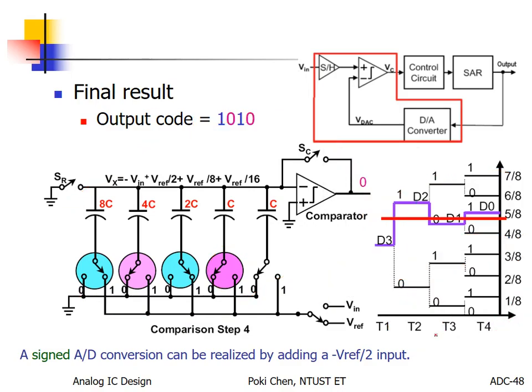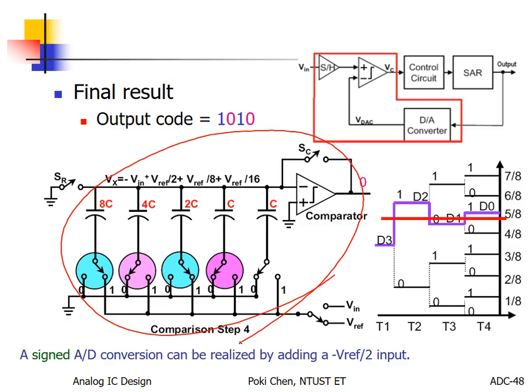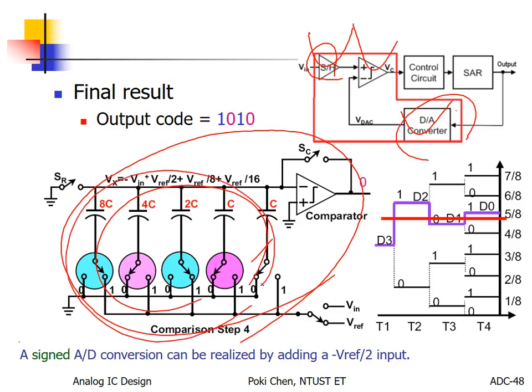Actually, this analog part is used for all those three. Okay? It replaces all, 3 in 1. How can I say replace? The function is 3 in 1. Sample and hold, right? On the capacitor array. DAC, also on the capacitor array, right? And then comparator here. See?